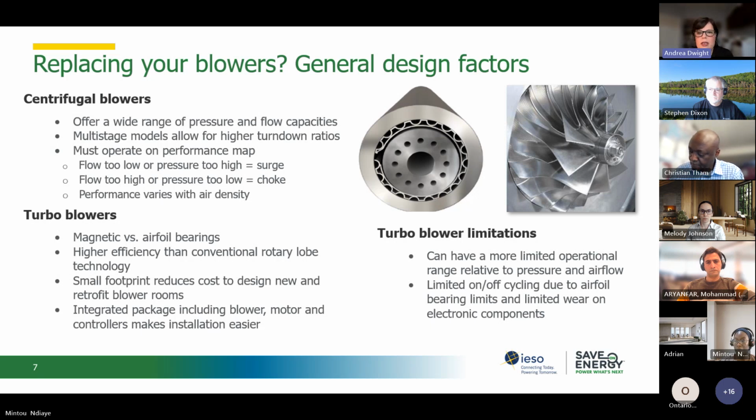Turbo blowers have many advantages, including the fact that they have a very small footprint. They come in an integrated package that is pretty easy to install. But you do have to make some decisions around which kind of bearings you wish to use, magnetic or airfoil. And there are some circumstances where they don't run that well. They don't like being turned off and on a whole lot. So depending on your situation, you'll need to take a look at what's best for you.